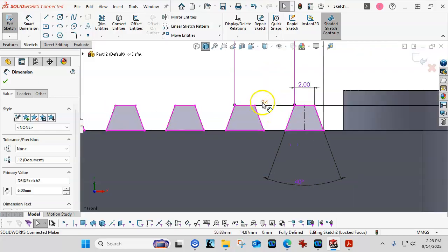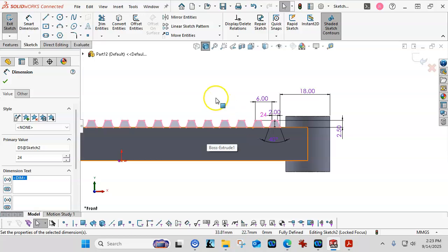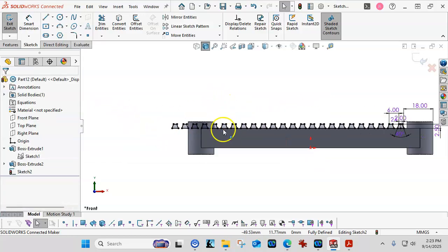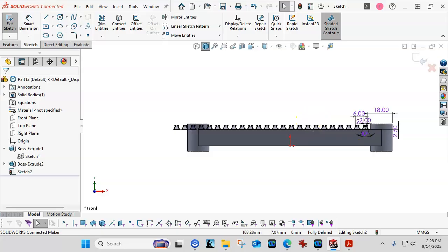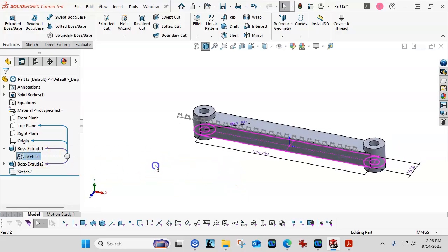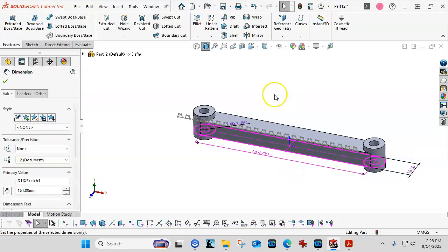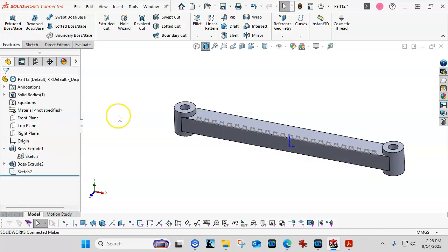The gear really doesn't care as far as that point to that point or that point to that point. It's whatever gives you the functionality. So I told it that there was 24 teeth, and we ended up with a little bit less. So either I missed the dimension. Oh, I can't type. That's never happened before. So let's just go ahead and accept. I want to see the, there it went, 134, 164. We go ahead and rebuild it. That looks a little bit better.